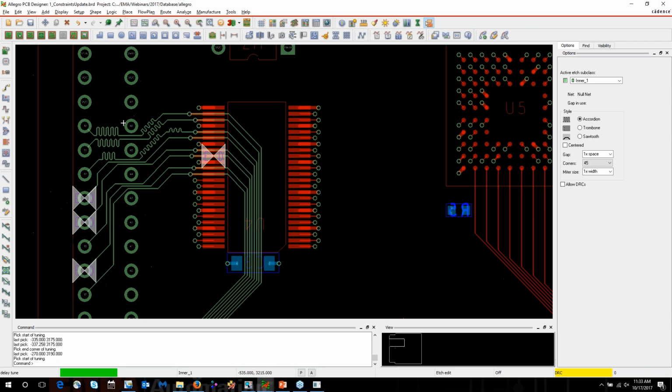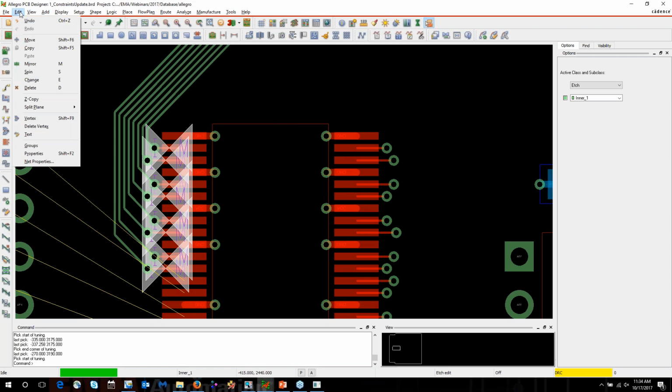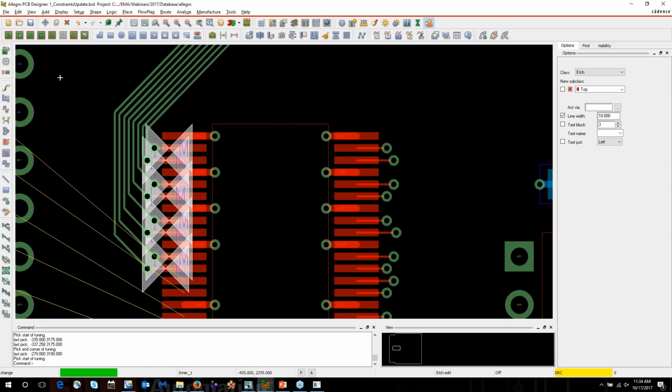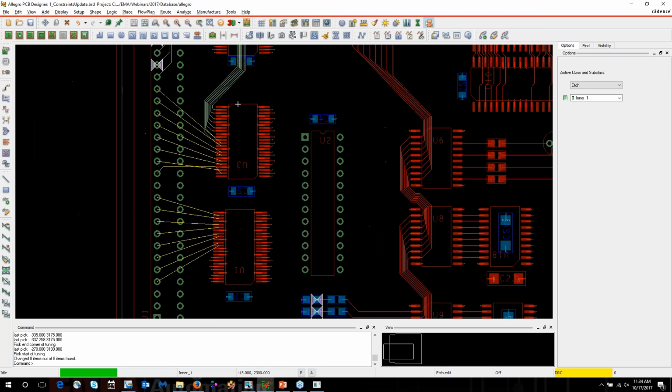There we go. So that's enough for now. Oh, our impedance. If we float the cursor over the DRC, you can see that it's supposed to be 60 ohm, which is what we set in CM for OrCAD. And it's actually more like 81, which means we have to make our trace a fair amount fatter. So it's complaining about the ones on the top layer. So let's just do an edit change and set these trace widths to 10 mils. And there we go. Okay.